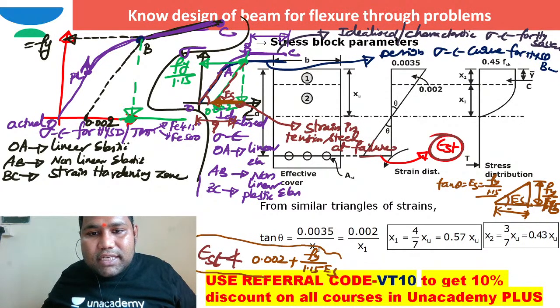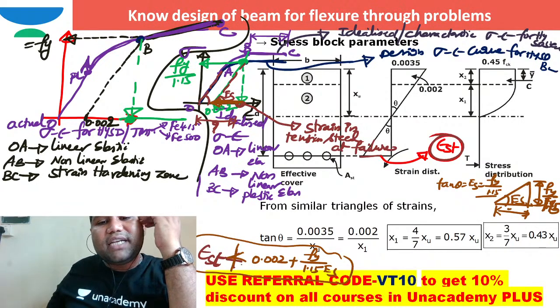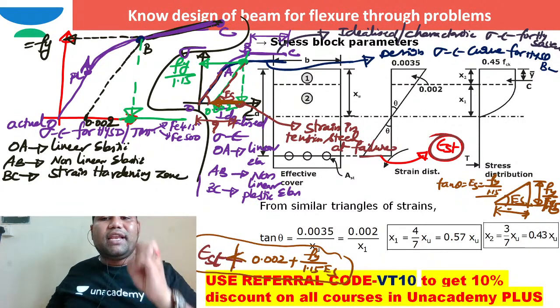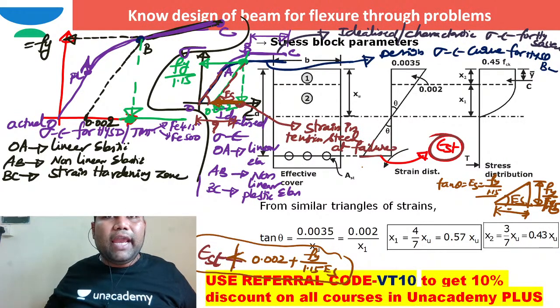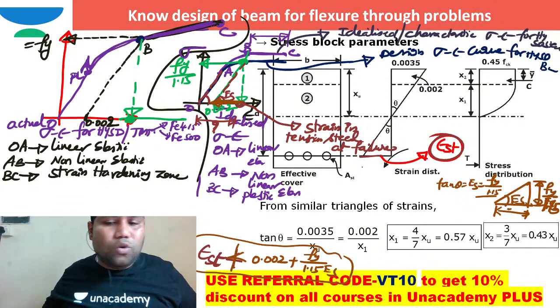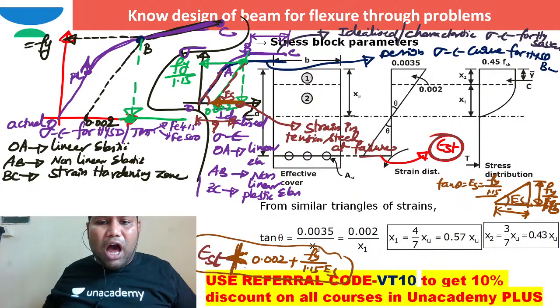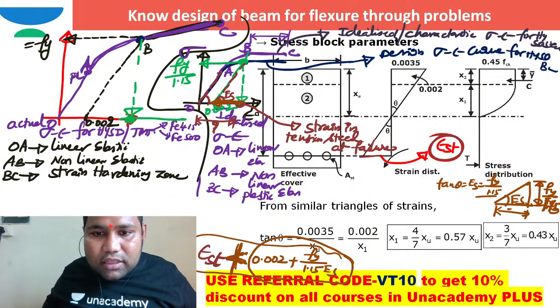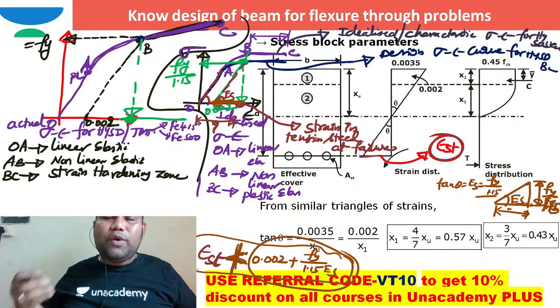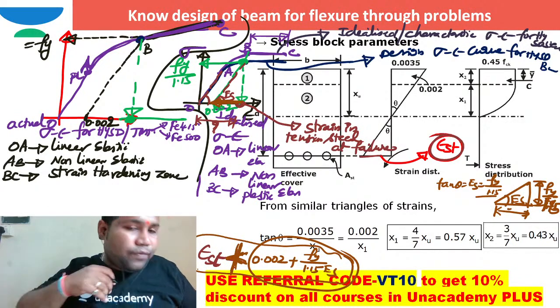So the strain in steel should not be less than this value. Let us suppose the tensile strain in steel is less than this value, for example this value. In such a case the steel has not yielded much before failure, so the failure is sudden, which is not good. Always the strain in tension steel at the time of failure should be more than this value. If it is less than this value, it definitely won't give you a ductile failure, right?